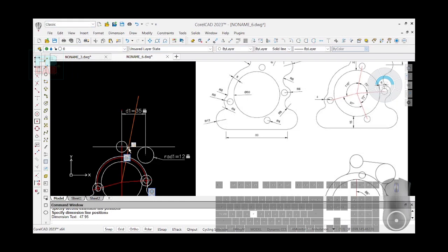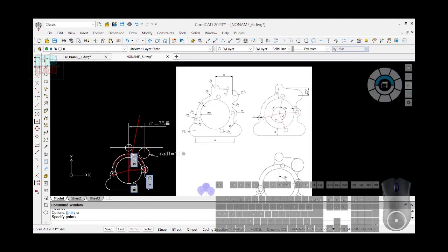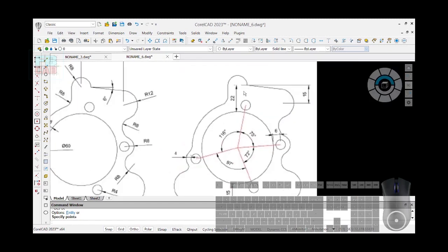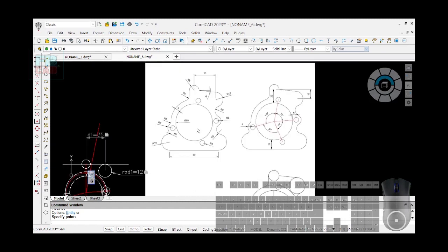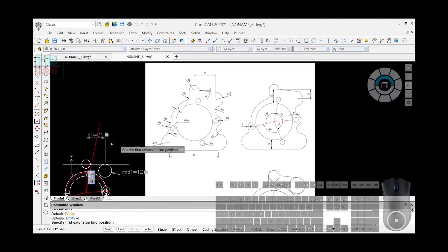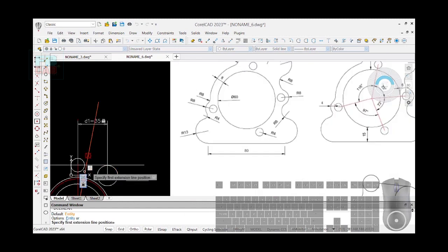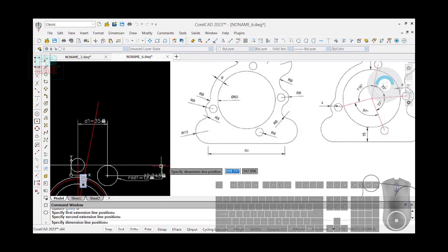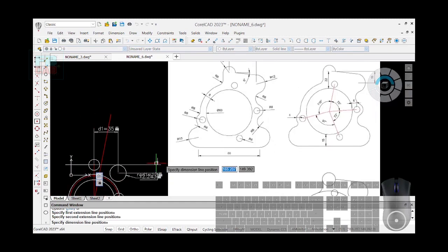Okay, geometric constraint fixed. I need to fix this guy so that he doesn't move. Okay, then the center of this to the center of this is 15. You're still going to use our dimensional constraint linear. So this and this ought to be 15.